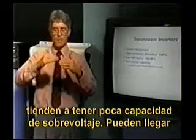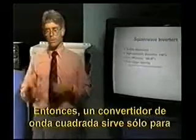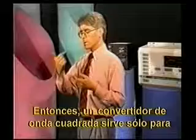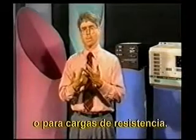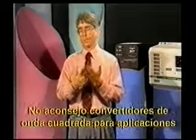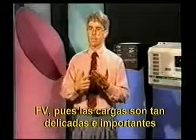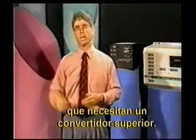They can surge maybe 10% or 20% above their peak rating. So a square wave type of inverter would be useful only for very small loads for very short amounts of time, or for purely resistive loads. In general, I don't recommend square wave inverters for photovoltaic applications. Typically, we're dealing with loads that are delicate enough and important enough that you need to step up to another type of inverter.